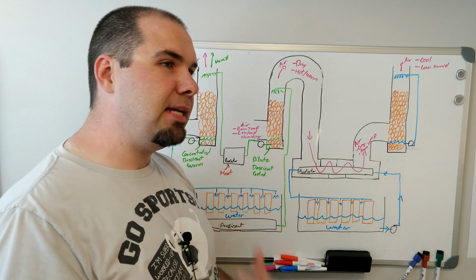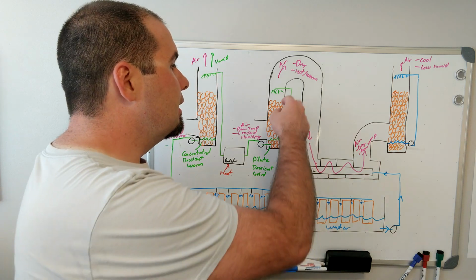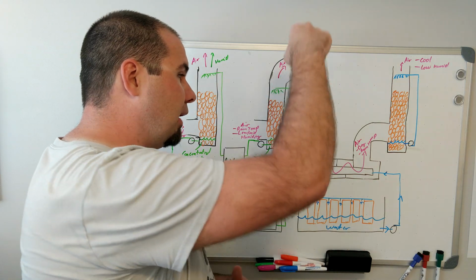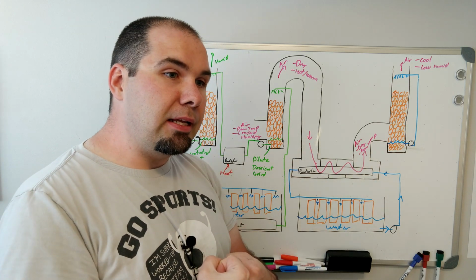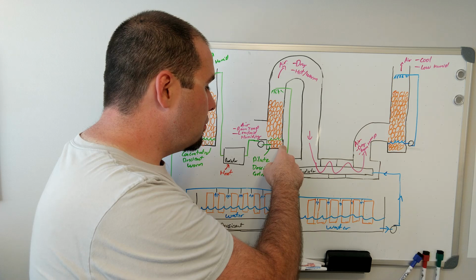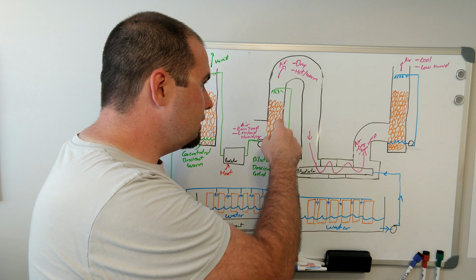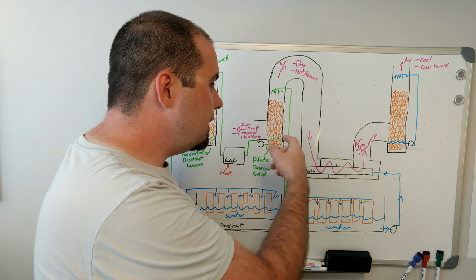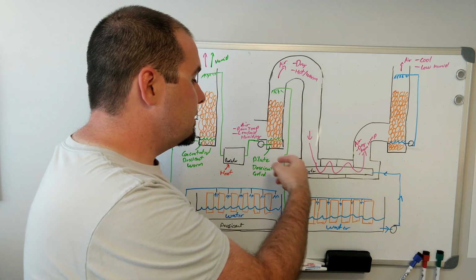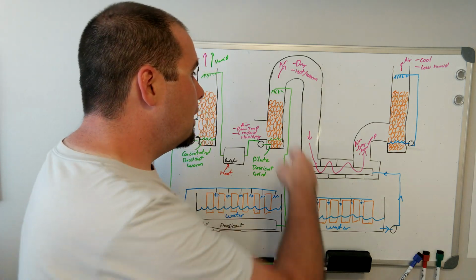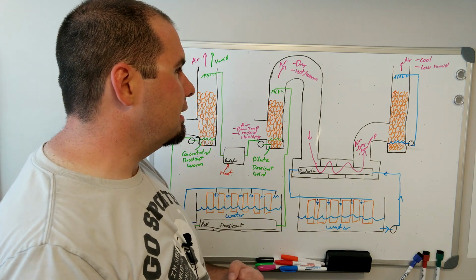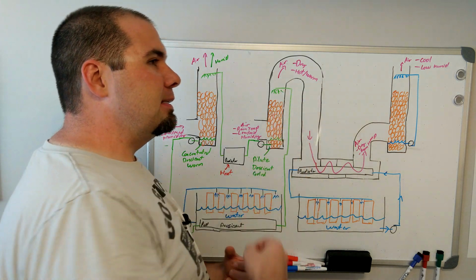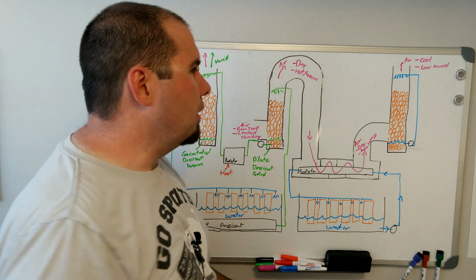And when we use a desiccant, we want to cool the desiccant, and as it sprays down, it pulls in humidity. It's still evaporative, so it's still losing energy, or I should say that evaporation is still taking in energy, but that pulling in the water with this liquid desiccant is, I guess, exothermic in a way.